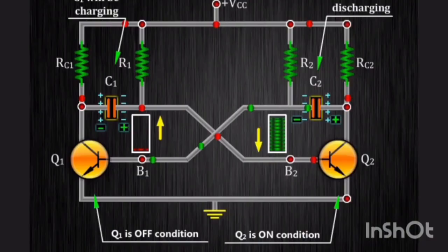Capacitor C1 discharges when the voltage is more than its voltage, and when it happens, transistor T2 is in the on state. When transistor T2 is on, the current goes through it and one of the LEDs blinks. The other one, T1, is in the off condition.